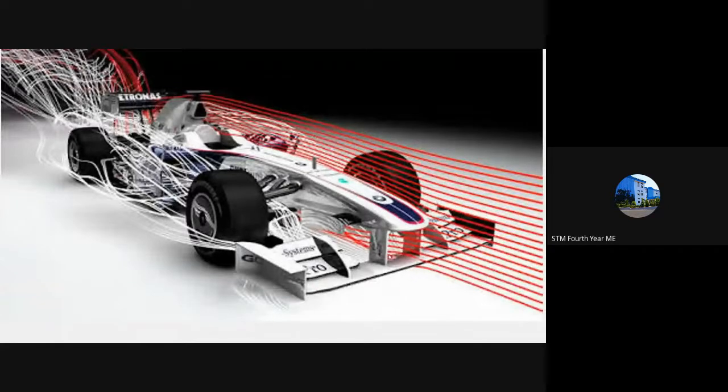So how are we directing the air? You can see the air being directed here. The air is then carried from here due to these shapes, or the aerodynamic designs that are provided, through the side of the vehicle and then to the rear. We are also providing a spoiler, which is another component, a negative lift aerofoil, which we'll be discussing. Due to this component, there will be a negative lift occurring at this point, thereby forcing the Formula One car onto the ground. So it always stays on the ground.